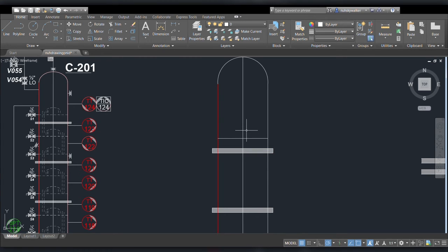In order for us to convert this normal line into a dotted line, we just have to left click this particular line, and then go to this particular button right here, the second one, not the first. Then we just have to click on Other, then click on Load, and choose the type of dash that we want. In this case, I'm just going to use ISO dash space right here,